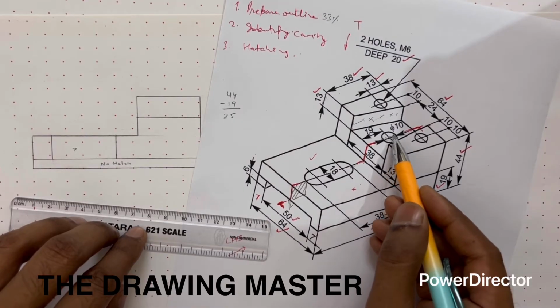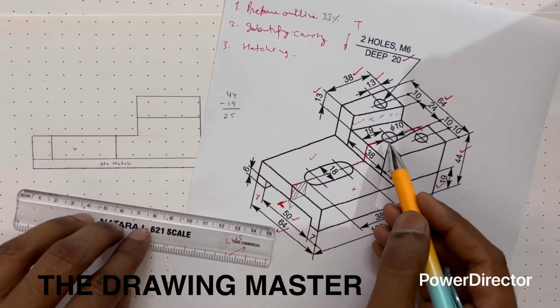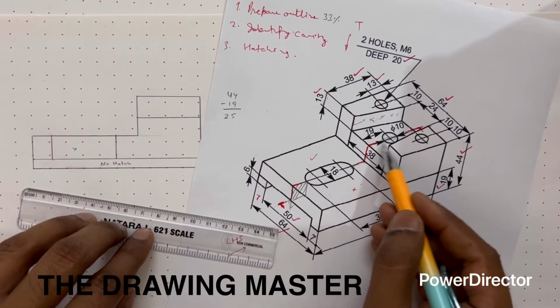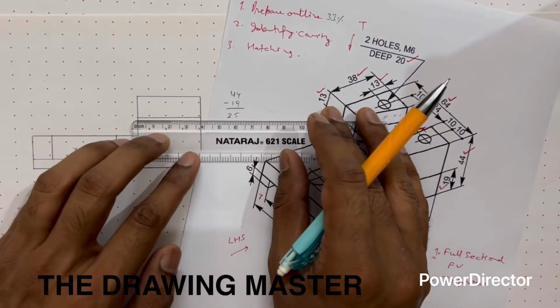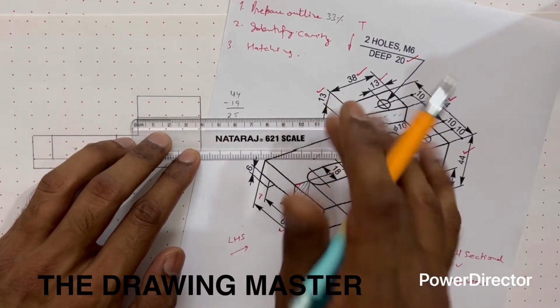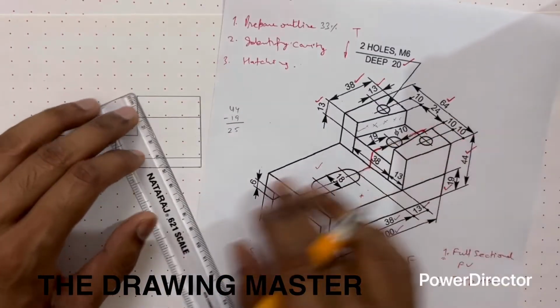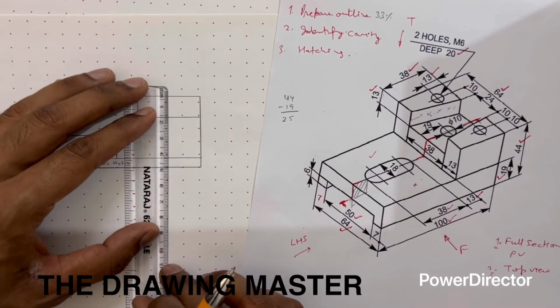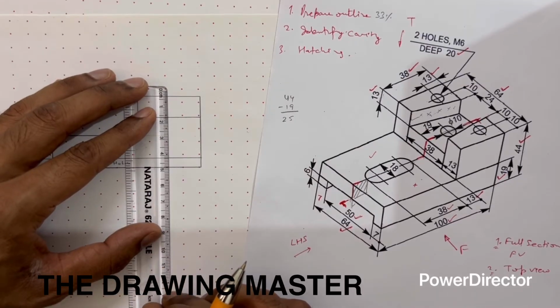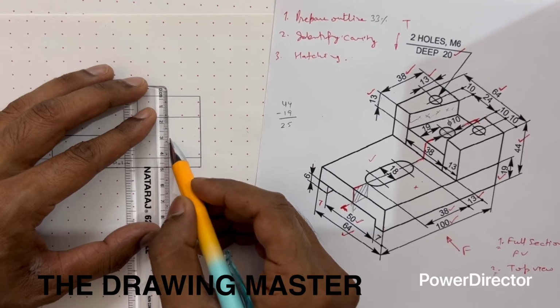So again, about this cutting plane, there is a circular hole. This cavity is there, dia 10, and this gap is 19, means half of this 38. So at 19 mm, mark the point. This is the center of this hole.